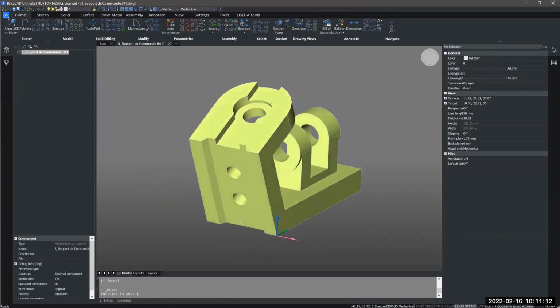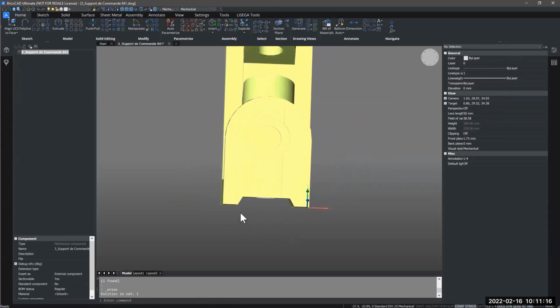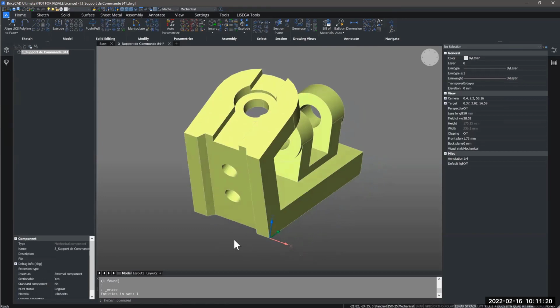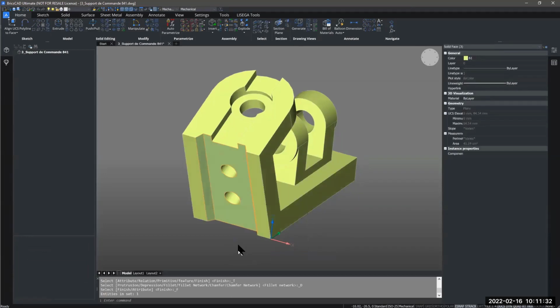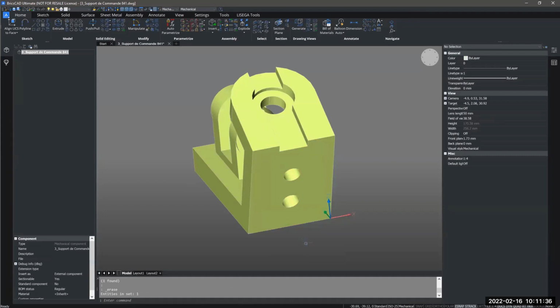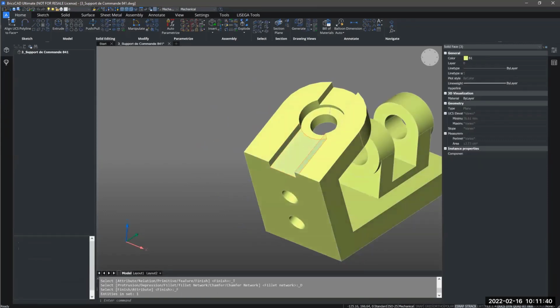In a similar fashion, we will delete and remove some of the extruded features here, such as the cutouts. To select this, you can select the faces manually as well, or you can hover over one of them, and through the select option, you can see the depression option. So we can select this, and it will select the surrounding faces and the bottom face of this for us. Once again, I can select delete, and it will be simplified for us.